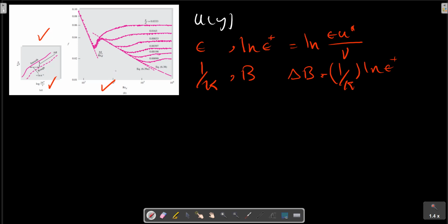You can see that laminar friction is unaffected, but turbulent friction, after an onset point, increases monotonically with the roughness ratio epsilon over D, which is shown here.